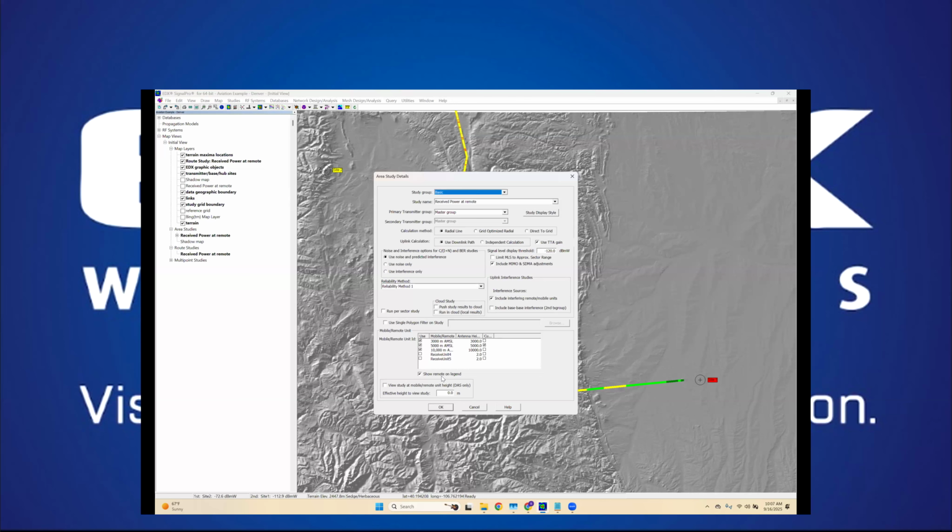But so most often, if we're looking at received power to the aircraft from those terrestrial base stations, this is my received power at remote. And if we were going to do what we would often consider an uplink study, the received power at base from remote, I ran into this terminology stumbling point a few years back, and so I always want to clarify.